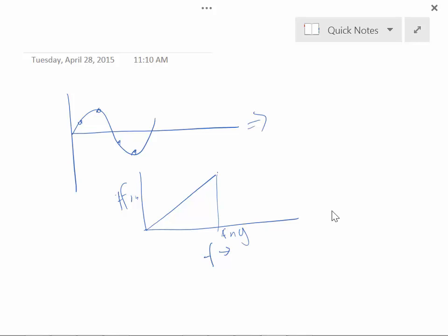It looks like this, but then it starts folding back over, and then it repeats right here. So if we sample at the exact same frequency, we get DC out. What we're going to find here is that this is 20 kHz right here. If we've got data here at, say, 30 kHz, that's going to show up as a 10 kilohertz signal.